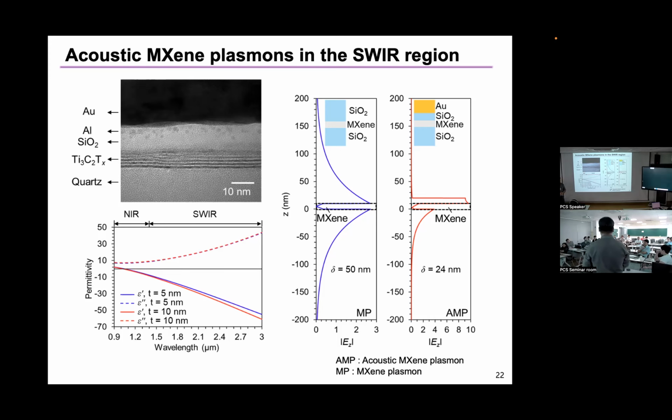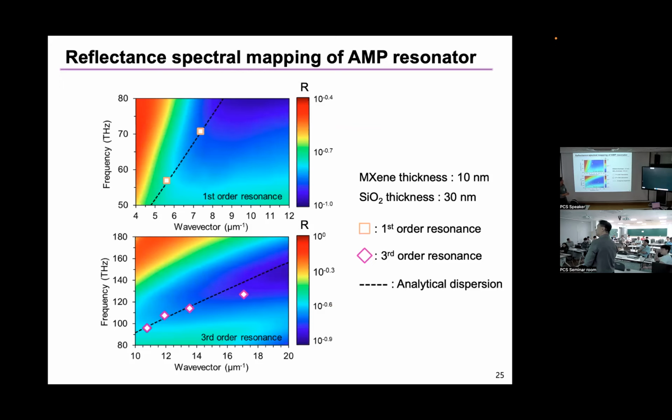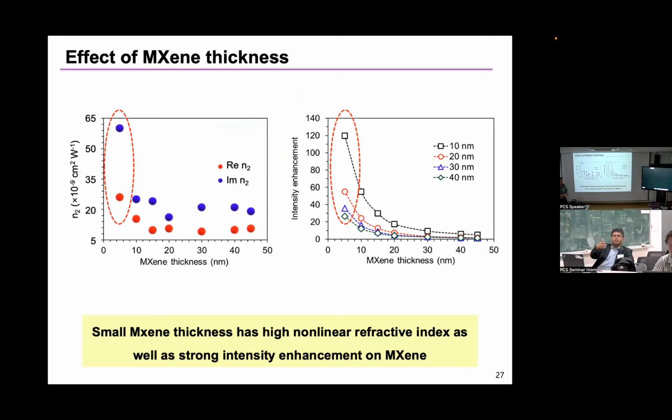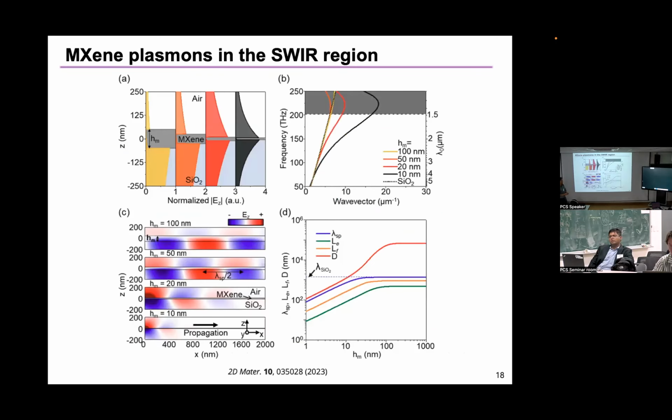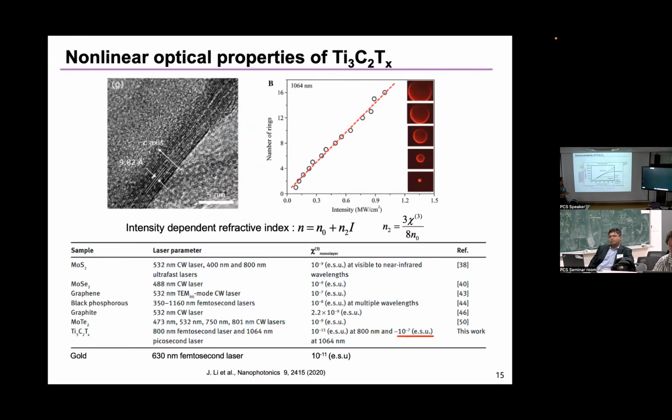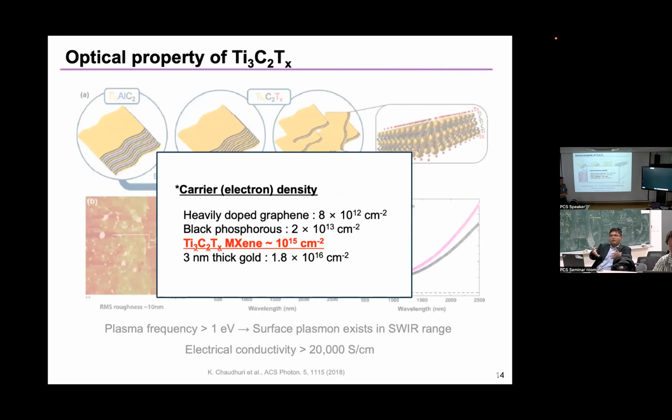The second question I have, which is related to this, is the carrier density that you determine, about 10 to the power 15 per square centimeter, right? It's a very impressive number. But I'm wondering, is this back calculated or back extracted from optical measurement, or is it something that you truly measure directly via some kind of Hall measurement?